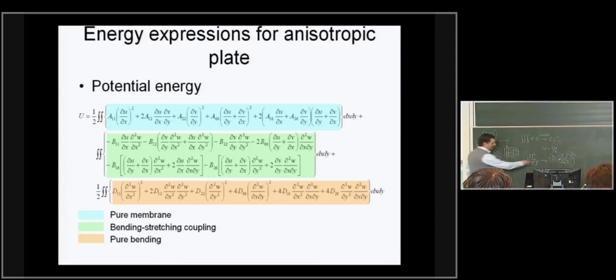In anisotropic I would expect to have terms like this, which means I have the second derivatives of w squared, which you can see are there, and then I have a D, which in an isotropic material is E h cubed, the thickness of the plate, over 12 times (1 minus nu squared). So if you're doing an isotropic material in bending, there is a term that will always appear, which is the D, the so-called D.